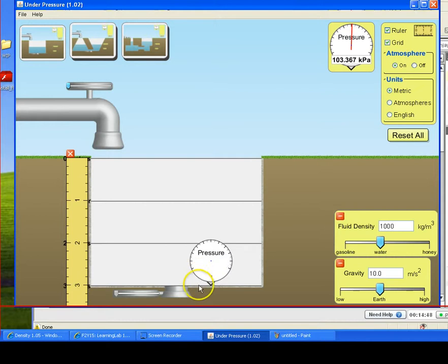Here, it's from this 3 meter mark at the bottom all the way to the top. So there's this extra difference between the 0 meter and the 3 meter line. That's the extra height of the air column, and that's why this registers a slightly higher pressure than the pressure at 0. Is this clear?